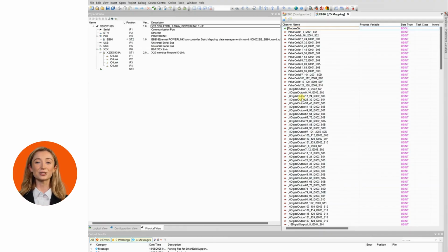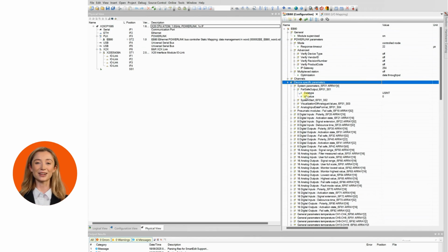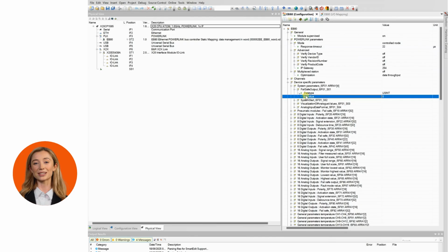The operating parameters are configured in the device-specific section by setting the init value field. System parameter configuration. Failsafe output. This function allows you to define the status of the digital output solenoid valves in the event of interrupted communication with the master.